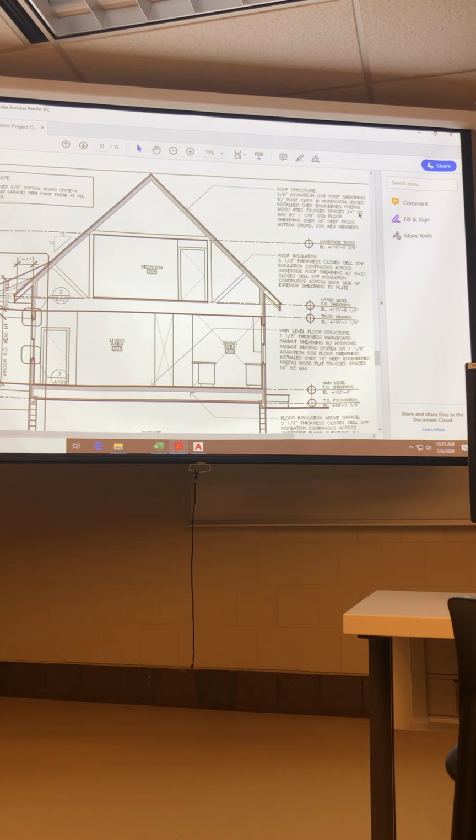So we actually have to increase the thickness of our floor sheathing beyond 3/4 of an inch to make it work. And in this case, we're using 1 1/8 inch OSB, another standard OSB thickness for our upper level top of sheathing. Okay, so I don't want to lose anybody in that little detail. We are using a different thickness for our exterior floor sheathing here, intentionally, with 1 1/8 inch OSB.